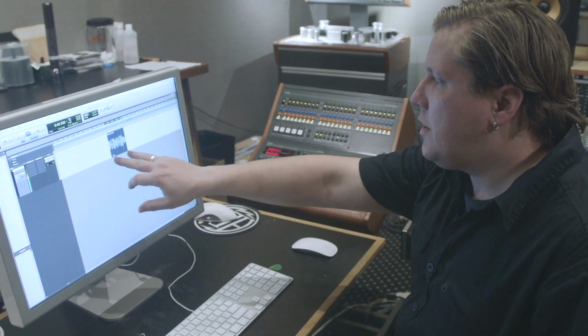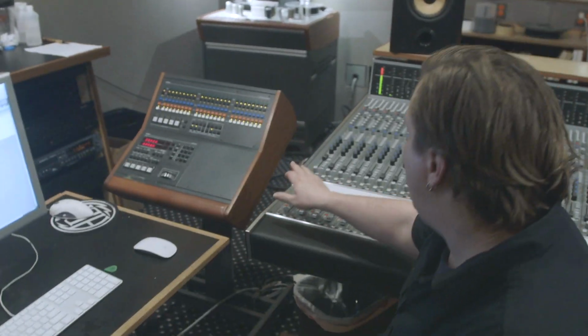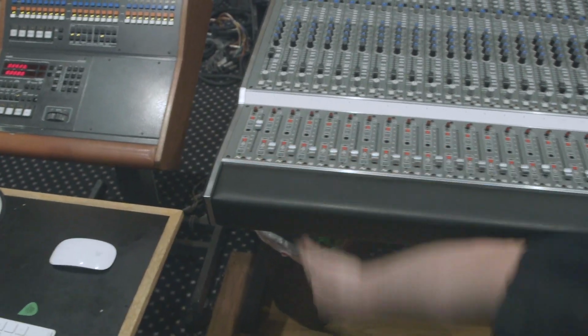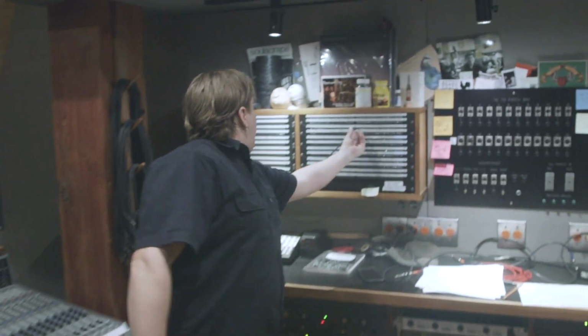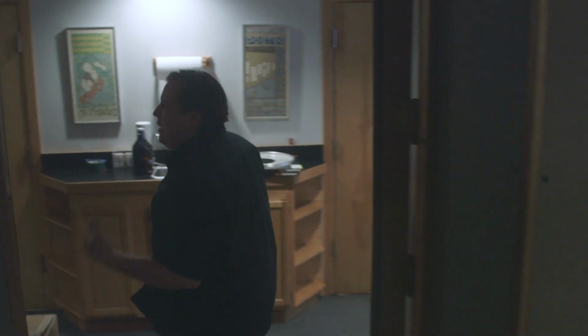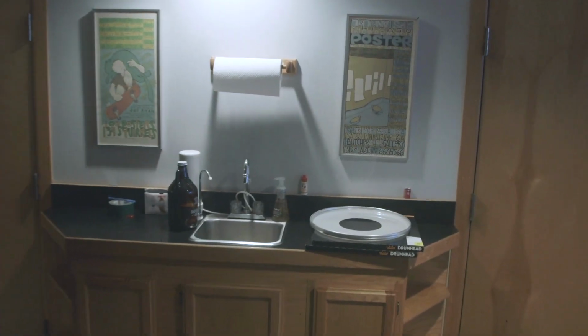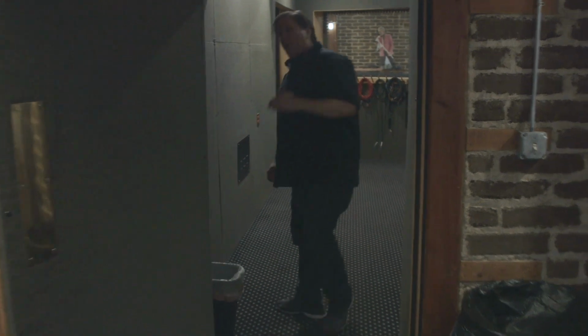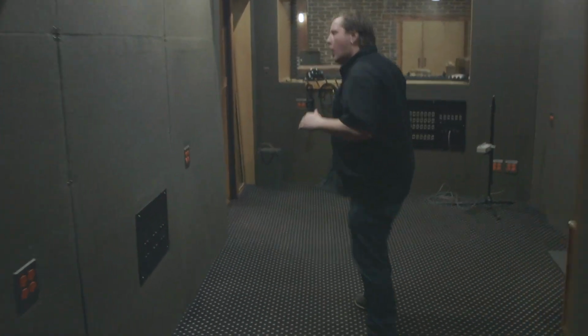So here we have a bass guitar loop going through the computer, into the console through the fader, and from the direct out of the console into one of the microphone tie lines in center field. And the idea of having that fader is so that we send it out at a signal that's not too quiet that it's making the amp hissier than it needs to be, but not too loud so that we're not overloading the amplifier as we go.